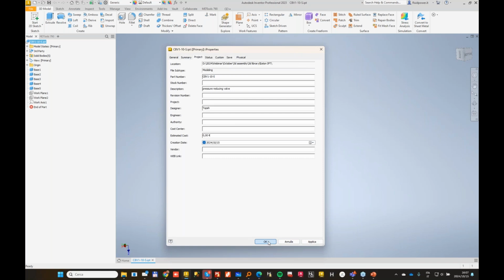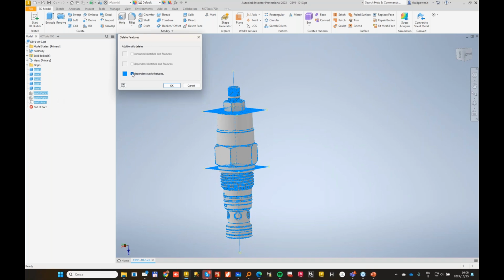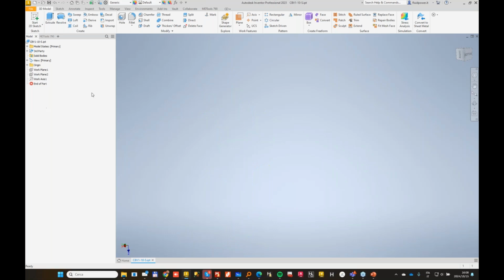If you have a PDM system, it will probably be easier to apply attributes from the PDM client, but now I'm working manually on each item. So that's easy for a part. A simple technique, which we'll see the value of in the footprint of the surface mounted valves, is this. If we just remove the bodies, this is particular to Inventor, it is possible to leave the unresolved entities in the part, but as you can see, they are still there. So even if we remove a geometry, these entities are recognized by MDTools for the automatic assembly.